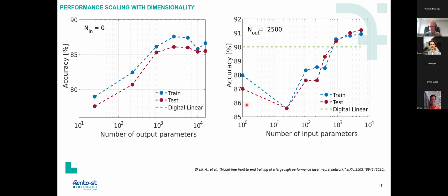Now we start training the input, and again we do the same trick with scanning the input parameters and the parameters of input and recurrent layer training. And we see a strong increase of performance, starting from this 85, 86 threshold without any input training, reaching now 91, significantly surpassing this linear threshold. Again, for our most beautiful device, we reached here 96.5% test accuracy for the MNIST, again without pre and post processing. And as far as I'm aware, for a fully analog system, this is the record so far achieved using electronic or optic whatsoever.